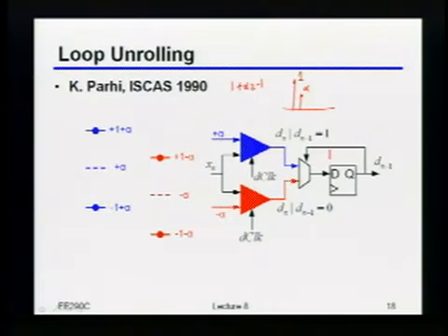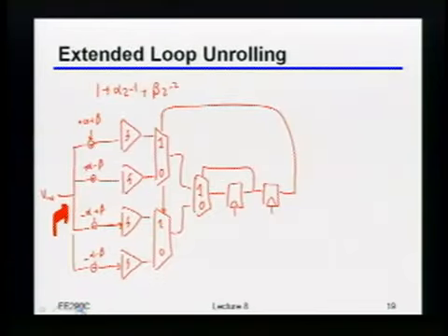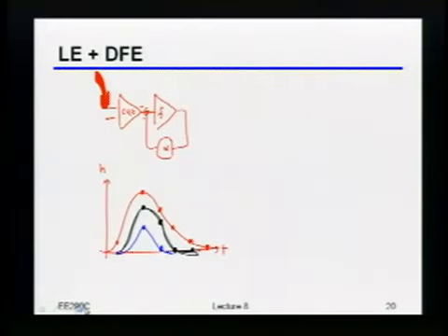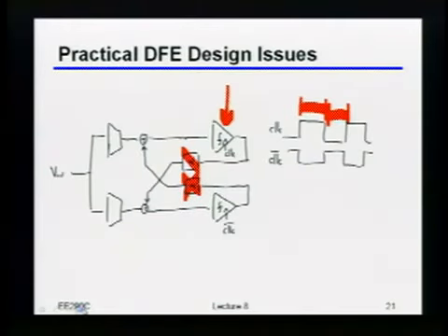But that indeed may actually be more relaxed than what you'd have to do to really physically close it. So it depends on which one of those ends up being the critical path. So indeed, if you end up doing a two-way interleaved, then you should probably go ahead and do the loop unroll as well. Because if you don't, then it may not really be buying you all that much, unless generating a clock that fast is really expensive. Does that make more sense now?